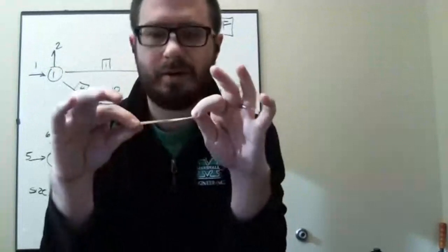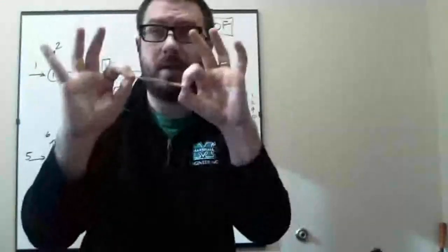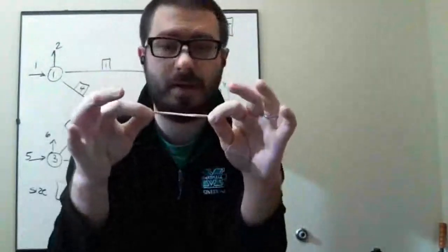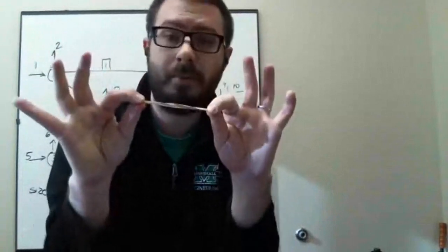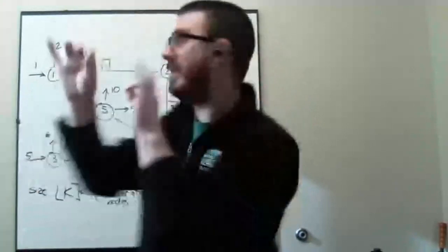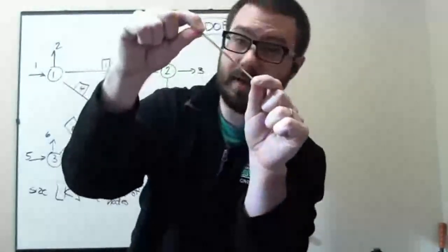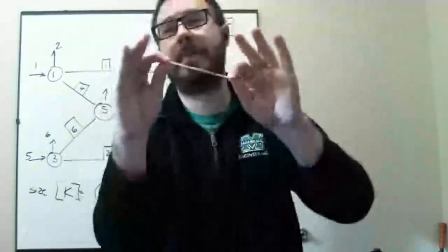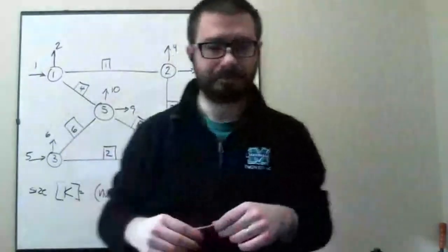So usually it's easier to define a coordinate system with respect to just the element, because I can define the mechanics of the element a lot easier if I'm just looking at an element at a time. But if I have an element that's sort of oriented like that, I want to assemble that in a big old system. Well, I got to use basically a little bit of trig to get this element that's at an angle, split those terms up into their sines and cosines so that I can assemble it with the whole system.